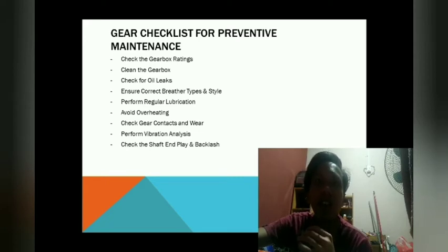Next, ensure correct breather type and style. You should ensure whether the breather of proper type and style is employed. This helps keep dust, water and debris from entering the gearbox and allows it to breathe easily.